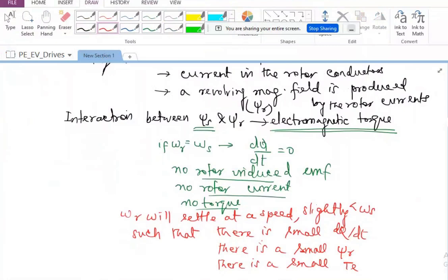But the only problem is, in a permanent magnet synchronous machine, you have a magnetic field available from the rotor side also. Whereas here, the rotor gets flux only because of induction. So obviously, we will have some limitation in terms of how much current is required to create the flux in both stator and rotor, and how large the air gap between stator and rotor can be.